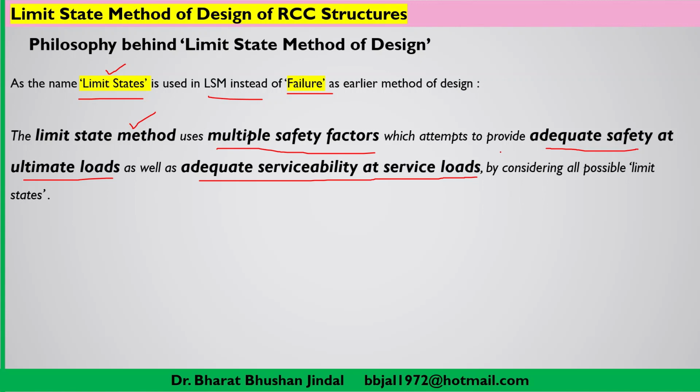Earlier in the working stress method we were concerned about only adequate safety, but here in the limit state method we are using an additional safety measure, that is, adequate serviceability at service load, by considering all possible limit states. So what are the limit states? What type of limits are we imposing in the case of the limit state method? Let us go through.